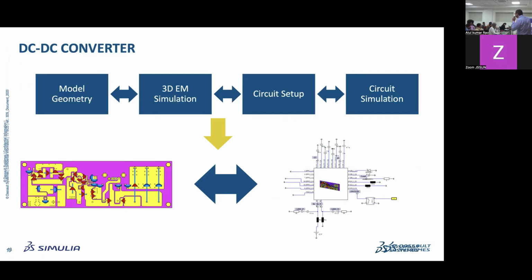Here we have connected basic lumped components and those non-linear elements. So will this result be only for S-parameters, or will it give voltage and current also? It will give voltage and current also, in CST, if you use the schematic. Once you connect the schematic, you put in probes at the points where you want to measure the voltage and current, and at that point you get the result, because the CE emission that we're talking about is how much voltage you are seeing at the LISN port. So we'll actually see that.